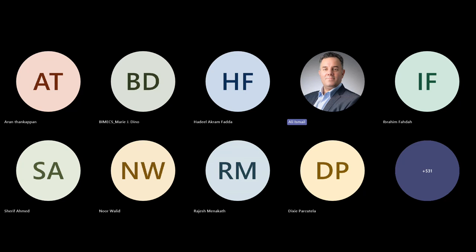This will help us to visualize these parameters and to check that the Civil Defense requirements are fulfilled. There is no calculation of the accumulated value of fire rating for finished material. This is a kind of input provided by the consultant, maybe in Revit as a family level or instance level parameter.